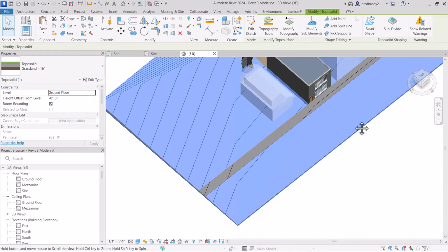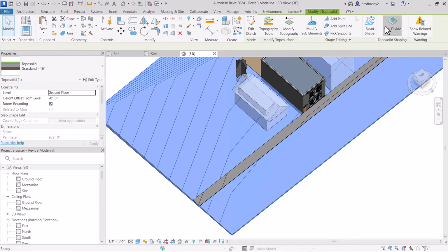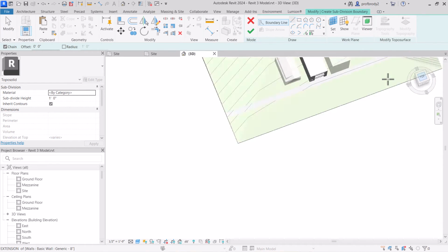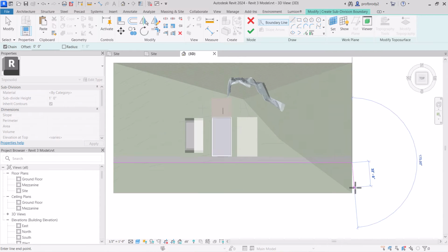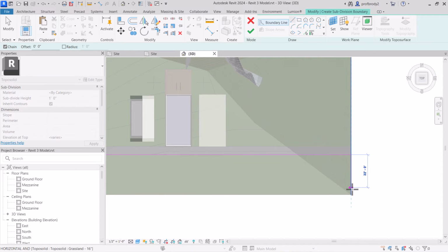Again, just select the site, choose Subdivide, and again, I would recommend being in top view, and in this case, maybe I'll draw it line by line so that I can control the dimension a little better. Let's say there's an 8-foot parking lane, and then a 12-foot drive, and maybe another 12 feet for the opposite direction. What did that all add up to? Probably 34.